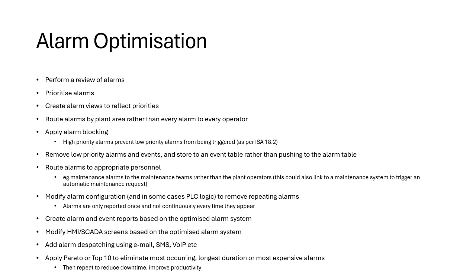There's a common movement now for flat HMI screens. We did some work with user experience and user interfaces when we were with GE, and what they were doing is they were making all of their screens very flat and muted, typically a grey screen, maybe a few colours but very minimal, and the idea is the operator can look at that screen, and if everything is grey or flat, they don't have to worry about everything because it's all in control.